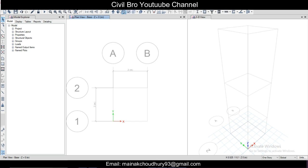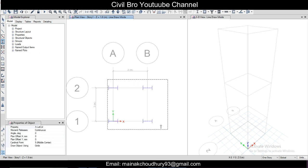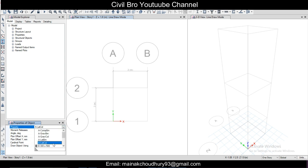So first of all, we'll just go to the plinth level, that is story 1, and here we'll just draw the columns. Let's do this very quickly. Just click here, put it on quick draw columns. So just draw it here, and before drawing, make sure you have taken the right property. In our case it is C400 by 400.